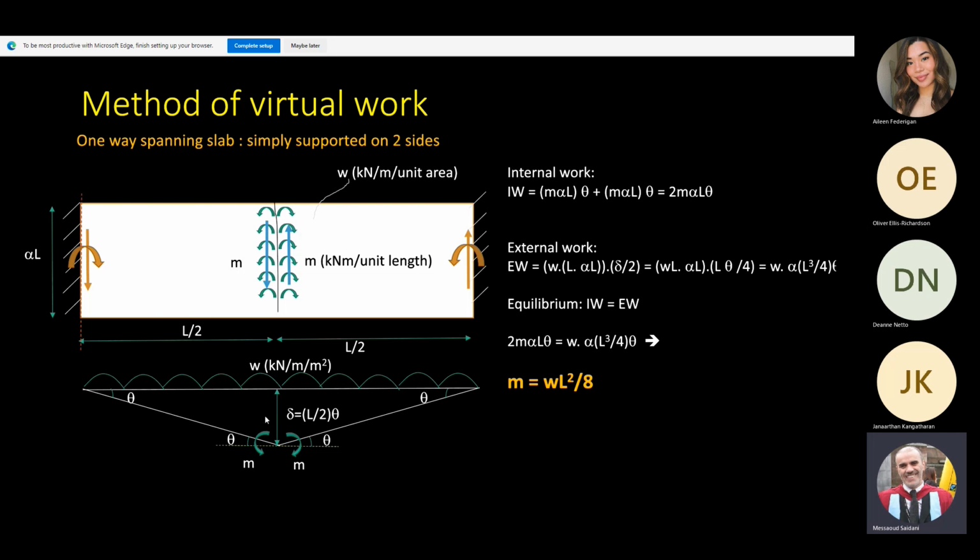Okay, there is a yield line in the middle, so we have theta and theta, M and M, so you have M theta plus M theta, except that you need to multiply by the length because of the units of the moment. Is that clear? Otherwise, you can see that it's really the same as the plastic theory. Okay, it's just because of the units, you need to multiply moments by length and UDL by area. Otherwise, it's the same. And you can see it here actually.